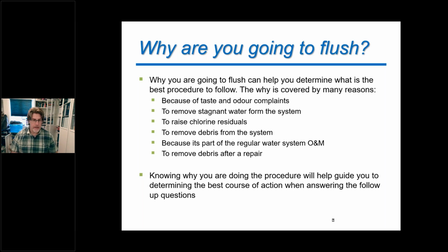Once again, is it just for chlorine residual? Is that what I'm looking for? Has there been an odor complaint or a taste complaint about the water? Or in our system, are we there to remove debris from the system? Is that what we're trying to achieve? Knowing why you're there really helps direct you to answering some other questions about the effectiveness of how you are going to do that flushing.